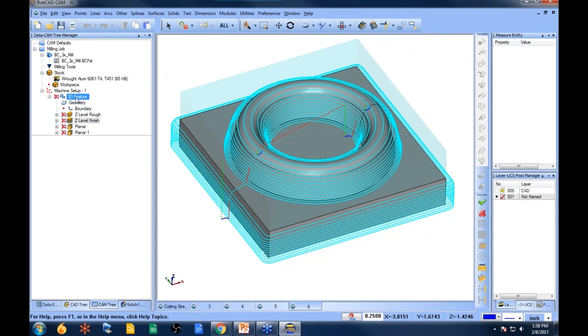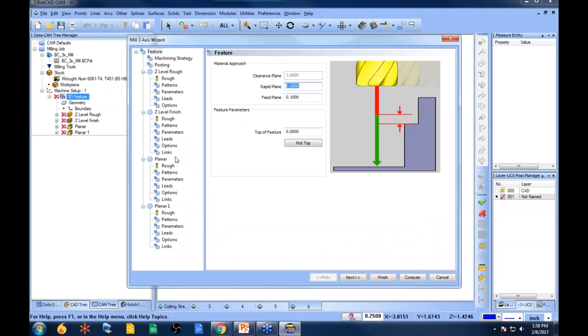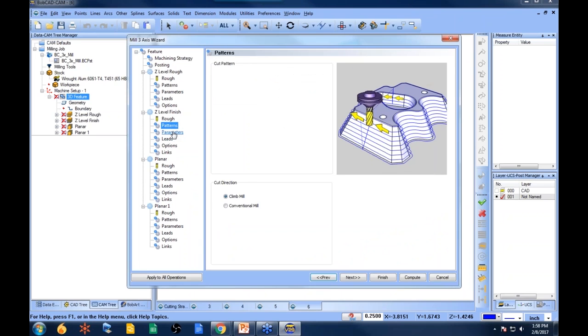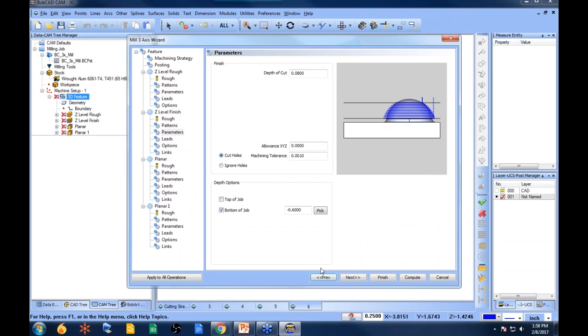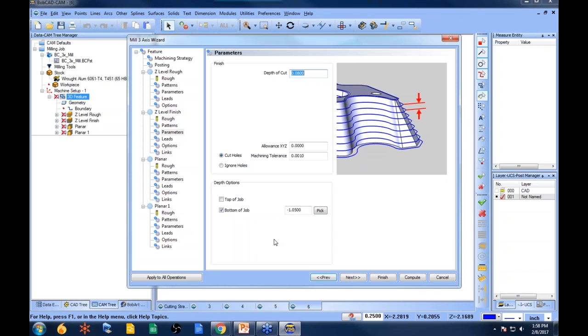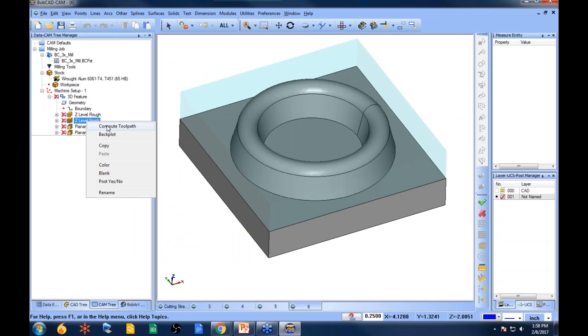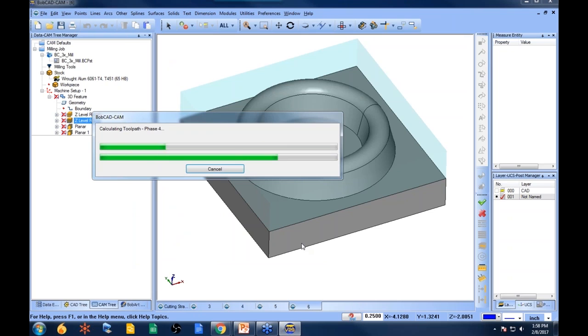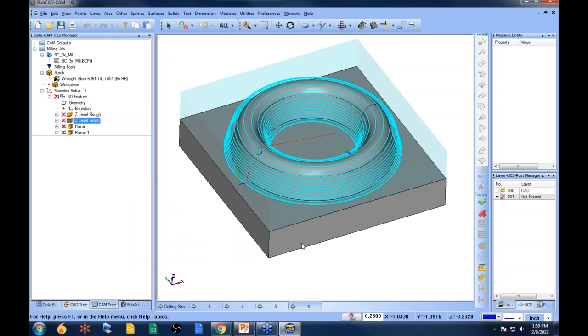So one of the things we would do is we would stop it from cutting down further. If we wanted it to run around the part as well, what we would do is create another feature for it. That's what I would do. Use one Z-level finish for one area and another Z-level finish for another area. When you get into linking in these scenarios, sometimes when you're going from a group, like this would be a group, to another group, you can run into issues with that. So that's just something that you guys need to be aware of.